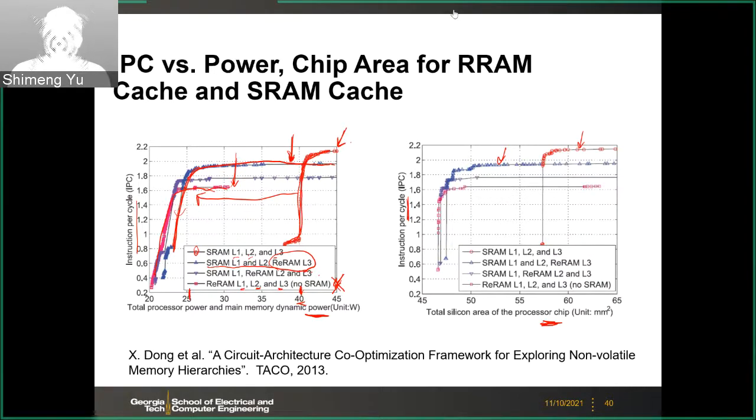So this is the main purpose for the system designer or the computer architect. You want to know the higher level design choices before you do the real tape out, right? So then you want to know what is the trade-off between the array subarray size. You want to define those parameters first, and then after you use this tool, you narrow down your design space to a few points, and then later you do the full design.